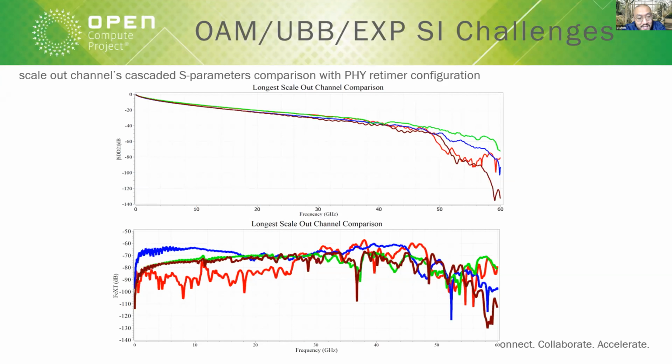This crosstalk is a power sum result, because in the via region crosstalk may dominate. However, we treated it using more advanced technology such as via in pad, also blind via, all those fancy technologies. And whenever we have space, we put additional ground shielding vias to shield the crosstalk. Then our crosstalk is very, very good in the post layout simulation.